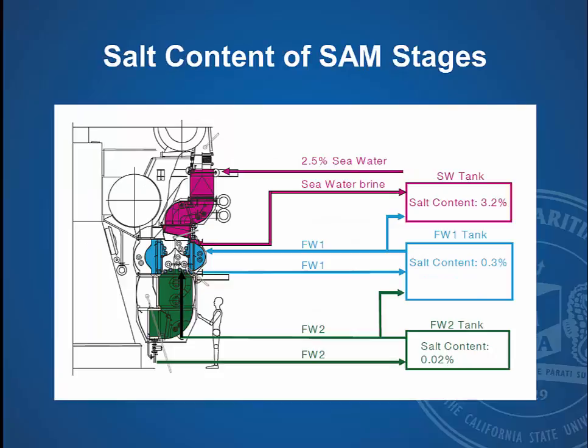So this is showing here what your salt contents are in each one of these tanks. And again, what you're trying to do is make sure that none of that salt is going to be able to get into the engine. So the sea salts, any of that mixing in, can mix with vanadium and some of the other things that come in with the fuel and can damage the engine. So you want to have that water entering clean.